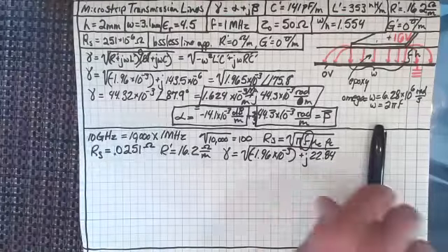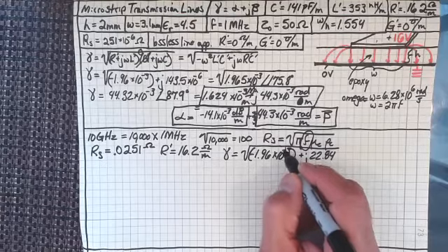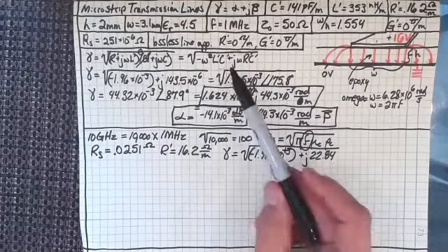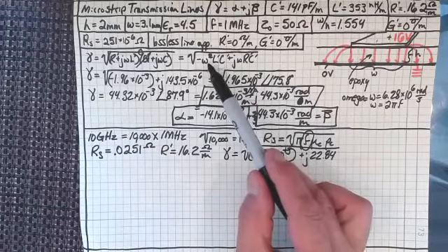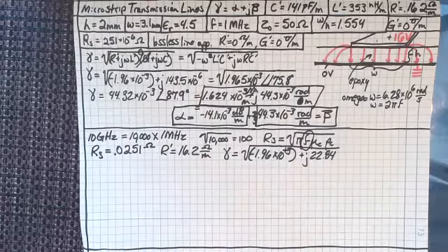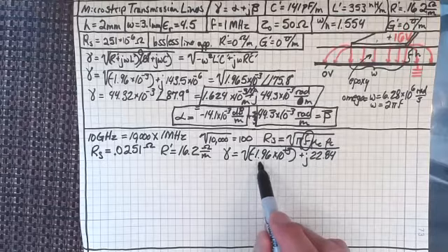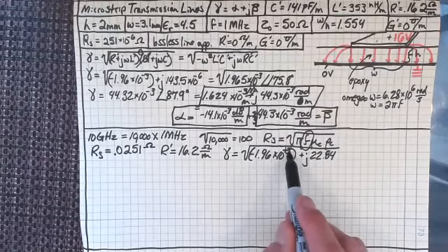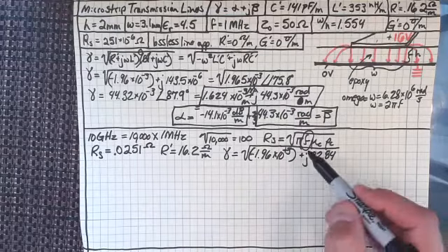Okay, I'm back again. Yes, I realized exactly what I did. That's not a minus 3, it's a plus 3, because it's omega squared. Of course, it's not going to be the same. This is 10 gigahertz squared as compared to 1 megahertz squared before. So that's crazy. Of course it's going to be different. So I get minus 1.96 times 10 to the positive 3, where that was minus 3 back there.